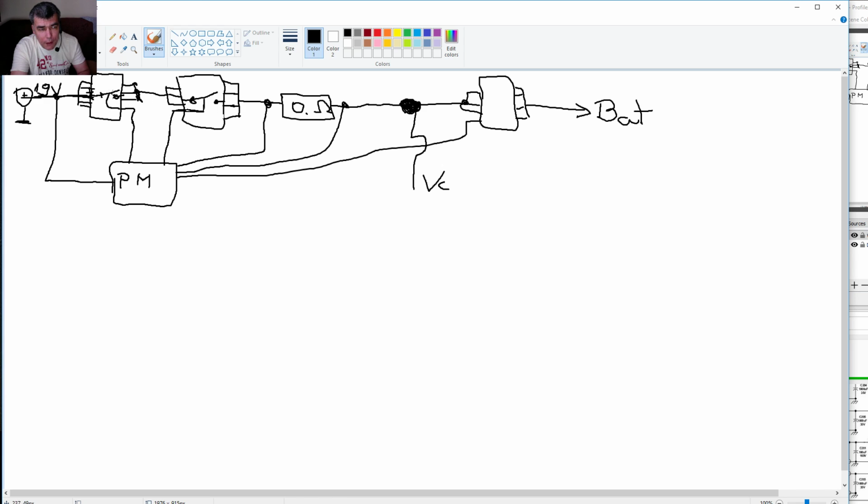So this is like a wire. When everything is fine, it's like a wire. There's no voltage reduction or anything like that. It's like a wire. That's these switches. So if you keep the power button pressed, this also has a connection with the thermal of the laptop. So if you have overheating, this switch will switch the laptop off. If you have a short on 5 volts on the USB ports, this switch will cut the power down.